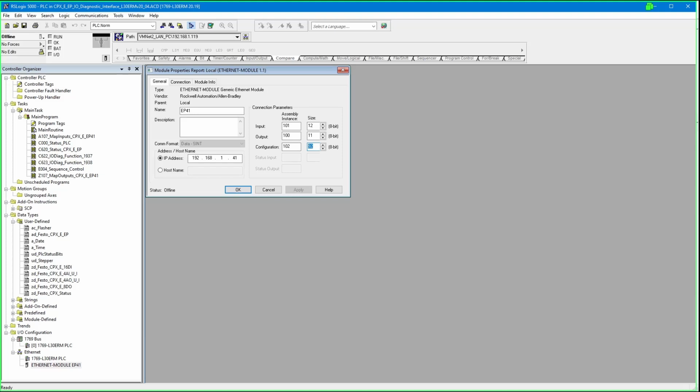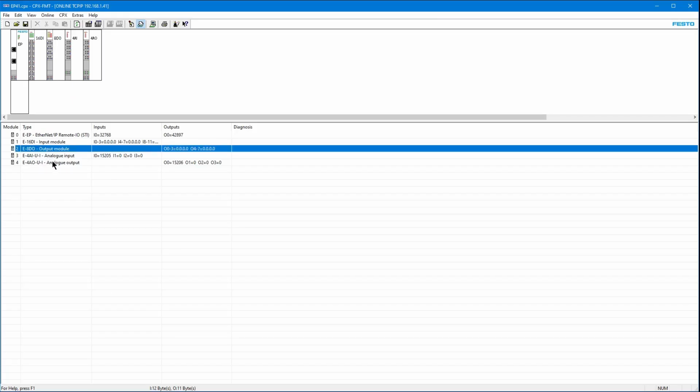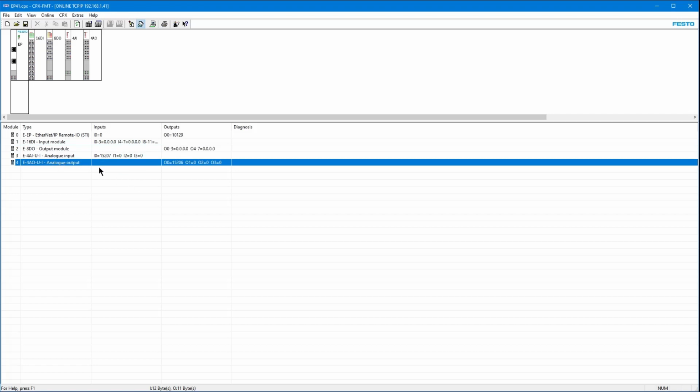And as I said, the whole purpose of the export is to modify all your parameters, and now you want to create a snapshot of this so that if any one of these modules are ever replaced, all the parameter data is stored in the PLC, and the PLC will download and overwrite the default parameters on startup.